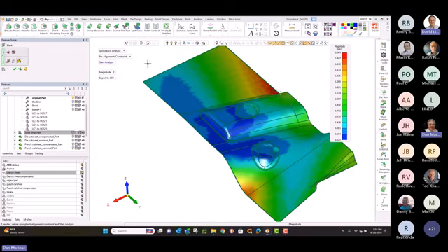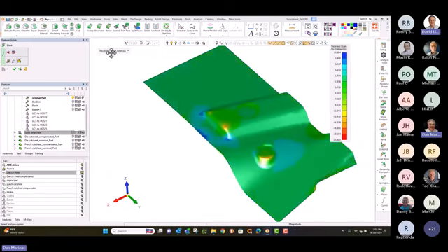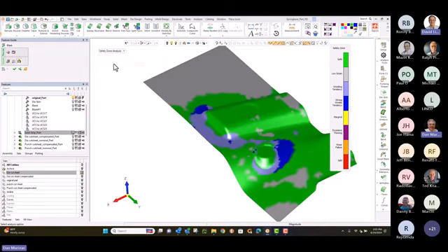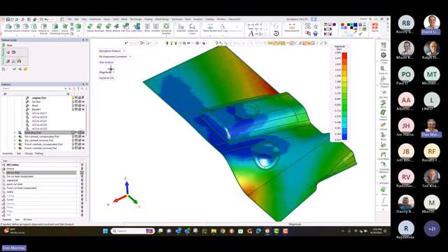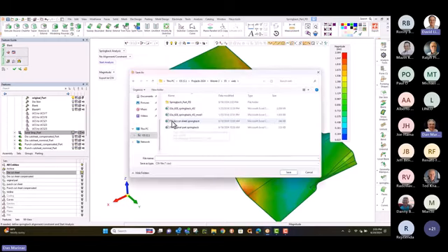Over in the red, you see there's as much as more like 2 millimeters in the magnitude, showing us how much that's going to spring back. We can look at the percentage of thickening and thinning, and also our safety zones, which are going to highlight the areas where it could likely wrinkle.